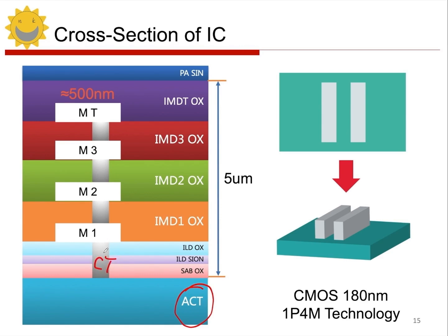Now the metals are on different layers, so they are separated in 3-dimensional space. Between the metal layers, there are insulating layers of different colors, which are made of silicon dioxide. Even though it looks like they are all stacked together when viewed from above, there is actually no electrical connection between them because they are isolated by insulating media.